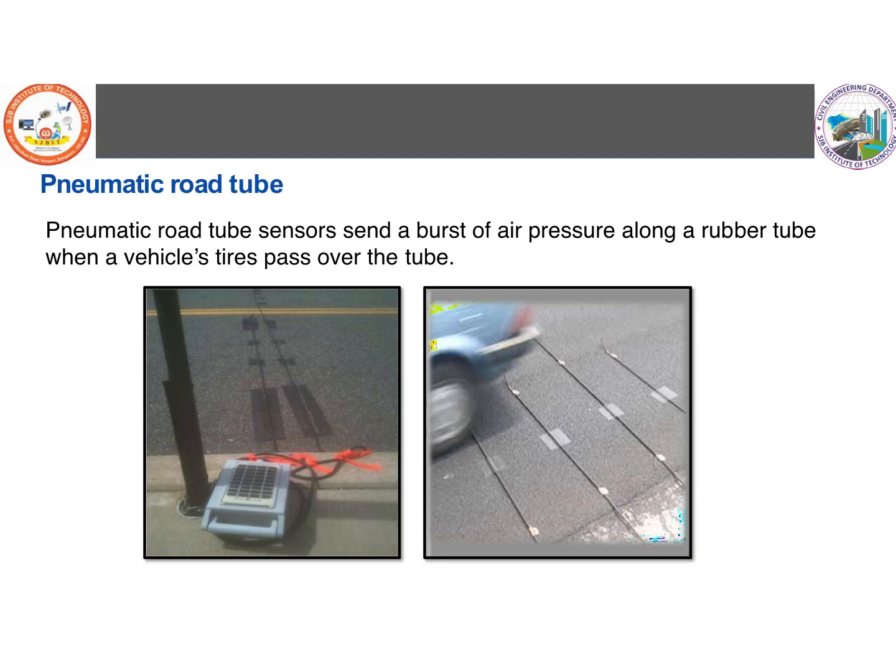Pneumatic tubes are small tubes. I hope you can see them here. These tubes send a signal that is connected to the automatic counting machines. Now what will happen when a vehicle passes the first pneumatic tube? Usually, in any vehicle you will have front wheels and rear wheels. When the front two wheels pass the first pneumatic tube, it sends a signal for one vehicle.